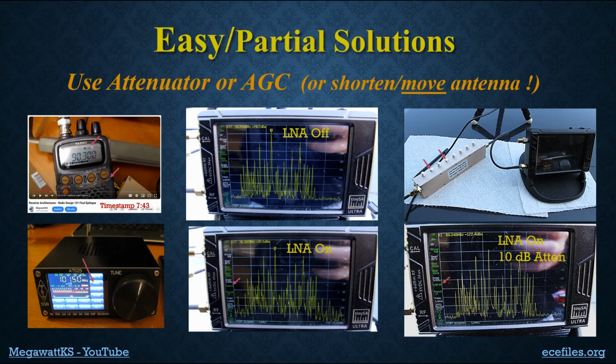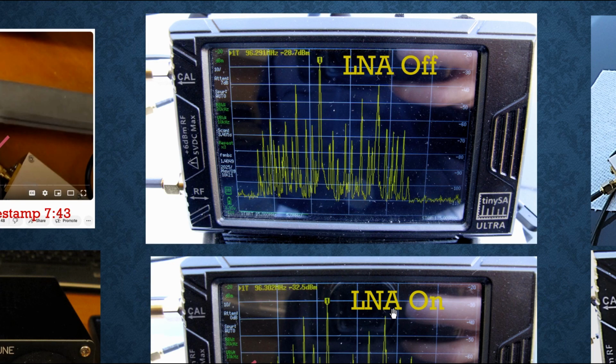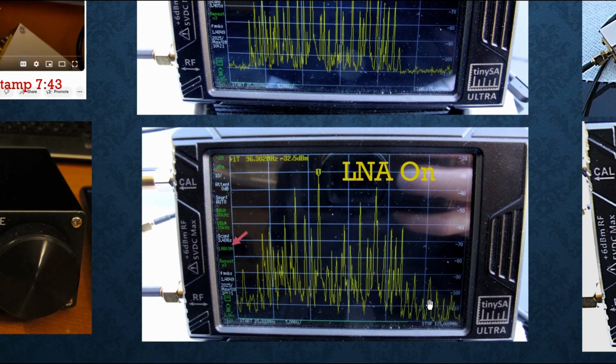And here's a demo that I did when I had a dipole antenna on the hood of my car outside, so it was away from most of the RFI. I used the Tiny SA Ultra and looked at the spectrum with the LNA off, and this is what I got. Then I turned the LNA on, and I got, well, we talked about that. Here the LNA is turned on. In both cases, I've got 0 dB attenuation.